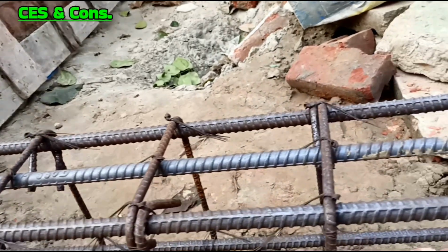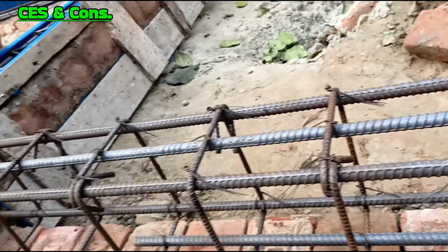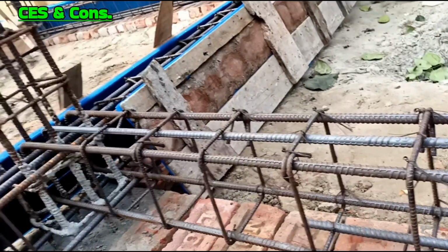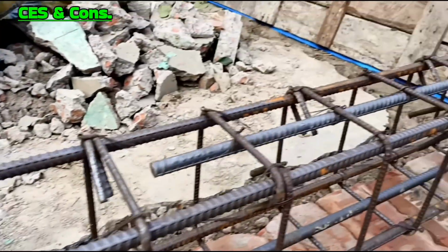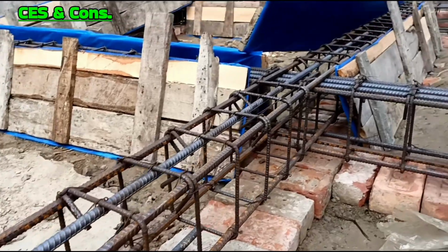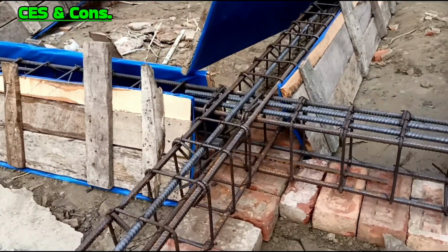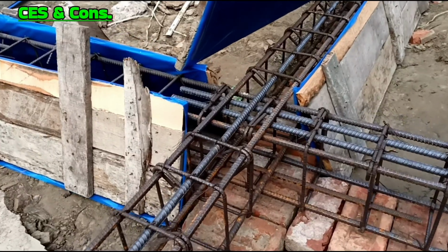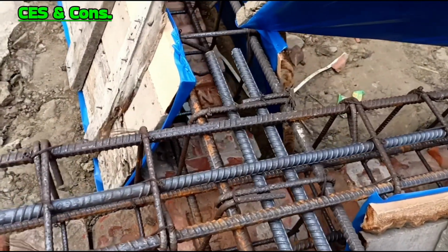At top, near all the supports, 1 number extra top bar of 16 mm dia has been provided to handle the hogging bending moment. As at the top of the beam compressive stress occurs, there is no need to provide any reinforcement for this compressive stress because concrete alone is sufficient to handle the compressive stress. But as a hanger bar or for construction stability, we have to provide minimum 2 numbers top bar longitudinally.